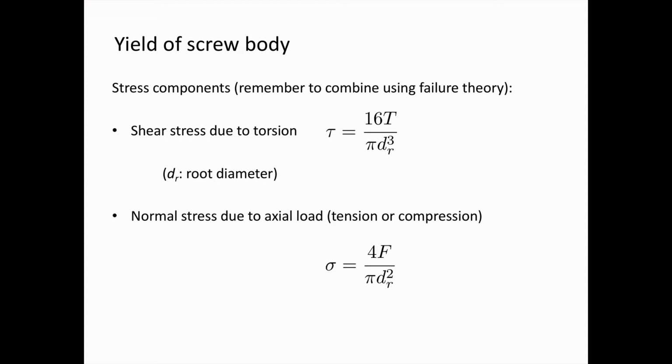Now, the next component is the normal stress due to axial load, and this can be either in tension or in compression. That's going to be equal to 4 times the axial force divided by pi times the root diameter squared.